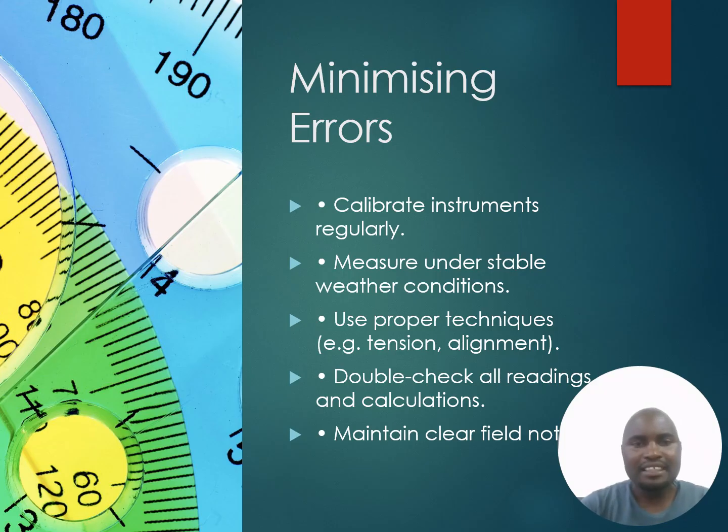For minimizing errors, as we said before, we calibrate instruments regularly, take measurements under suitable weather conditions, use proper techniques, e.g. tension and alignment, double check all readings and calculations, and maintain a clear field.